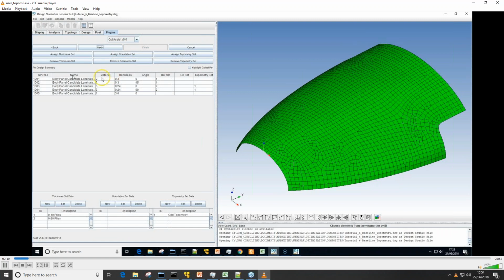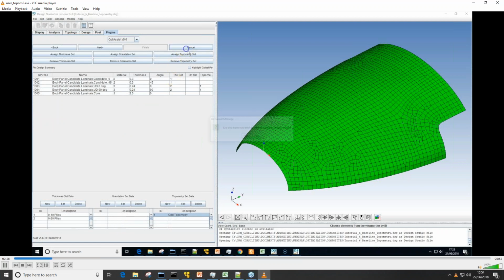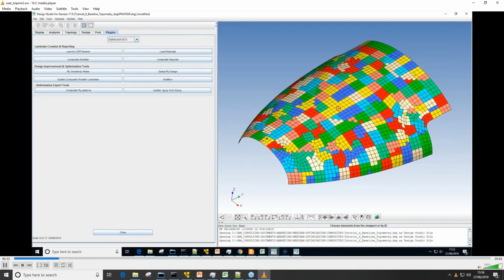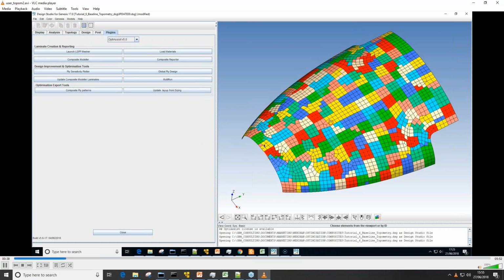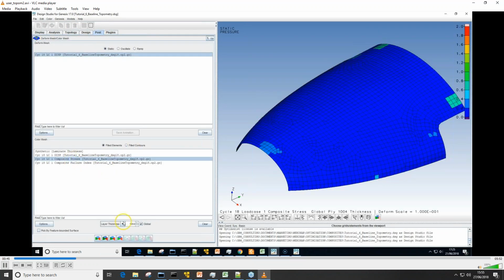And what we do, so I've taken this example which has got a classical topometry already set up for 2 plies. So we've got some UDs in 0 and 90, and this has got the standard 50 by 50 by 50 patch that we're putting in for our division of the ply shapes. So if I just hop across to the second model in this database, that's what Genesis is working with. So it's going to chop up the model into these patches in terms of the ply thicknesses, and then it'll gather those together into ply shapes once the optimization is complete.